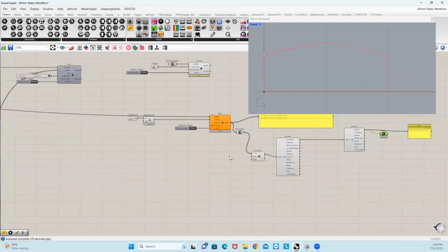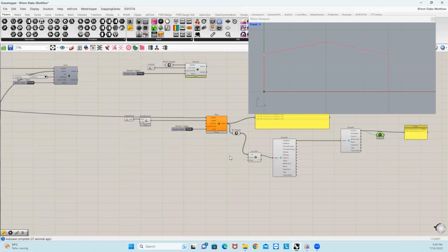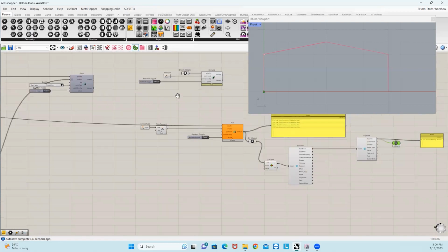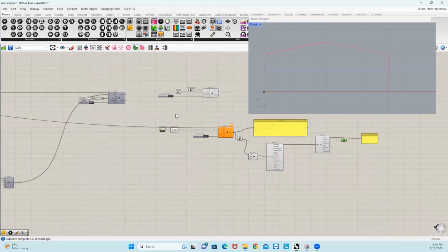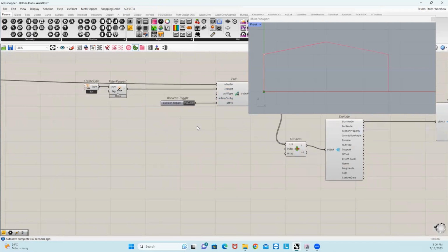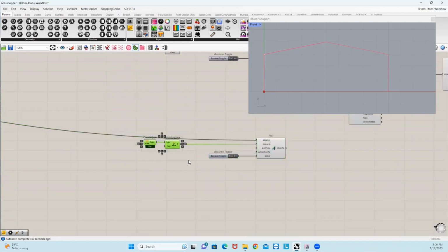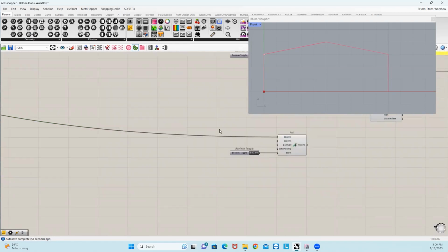So now we will create another pull request. In that one, we will extract the bar forces, like the moments, the shear force, and the axial force. So let me make this option false. I will just copy this one, remove this request.